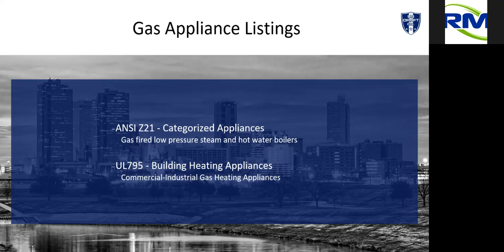795, if it has an external burner, something that can be changed out in the field, that is going to be most likely a UL 795 heating appliance. Now, there are exceptions to those rules, but that's a good general rule of thumb. So the nice thing is that the manufacturers are required to put it on their data sheet or on their sticker, as well as in their manuals.